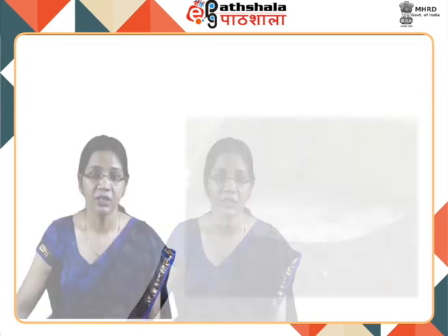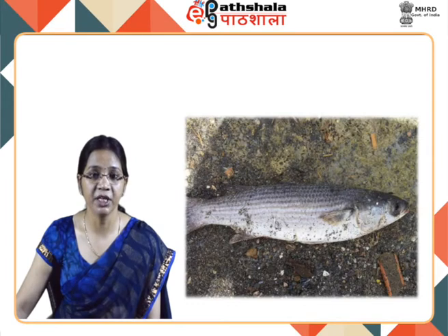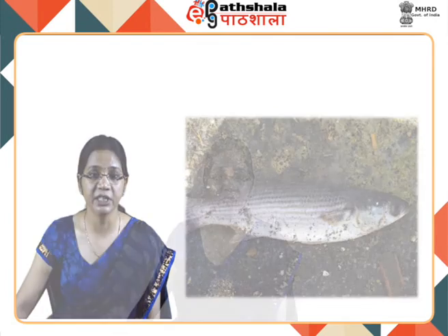Natural stream purification processes require adequate oxygen levels in order to provide for aerobic life forms. When the dissolved oxygen levels in water drop below 5 mg per liter, aquatic life is put under stress. The lower the concentration, the greater is the stress. Oxygen levels that remain below 1 to 2 ppm for a few hours can result in large fish kills.